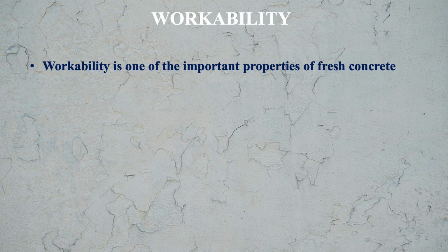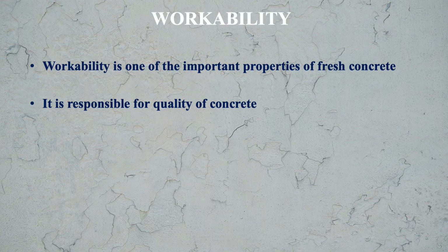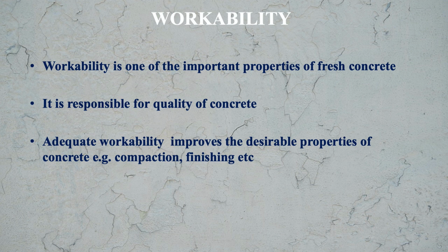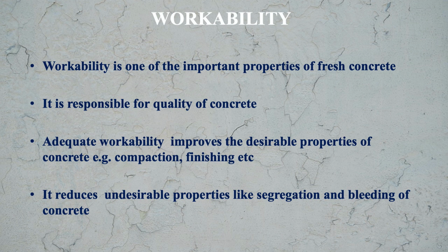Now workability is one of the important properties of fresh concrete, as you know. It is responsible for the quality of concrete, meaning it will govern the various properties and the quality of the concrete. Adequate workability improves the desirable properties of concrete, that is compaction, finishing, etc. It reduces undesirable properties like segregation and bleeding of the concrete. It means if the concrete mix is properly workable, then there are fewer chances of segregation and bleeding.